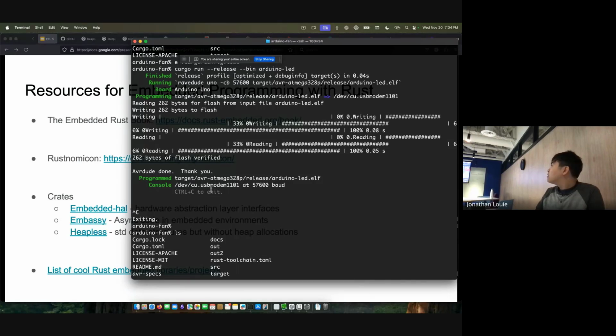Another thing people can do is, on this device for example, there's I2C. That's a very simple serial protocol that can get information as characters off of your device. So your logging example could be, ship this data into my I2C bus so that some other external thing that I physically attach to it can read that and then print that on the screen, and so on, right?